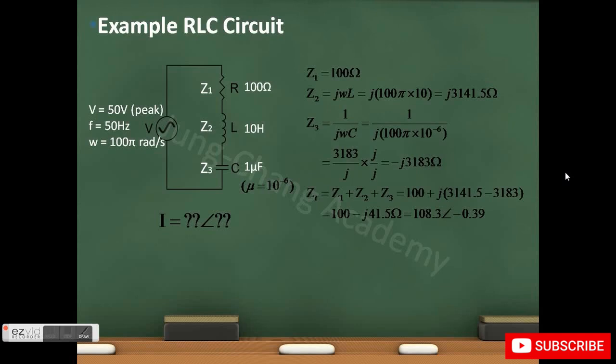To do this, first we need to determine the impedance of these three elements. So for the resistor, the impedance Z1 is just 100 ohms. And for the inductor, Z2 is j times omega times L, where omega is the angular frequency and L is the inductance. So when we sub in the values, we know that Z2 equals this. Now for the capacitor, the impedance is 1 over j omega C. Again, omega is the angular frequency and C is given here. So when we sub in the values, we know that Z3 equals this.